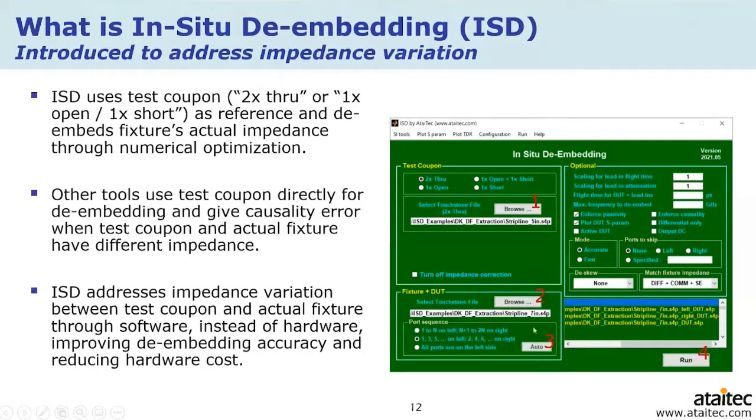It's going to give you a summary of the port connection and frequency number, etc., and then it's going to set the port sequence automatically. If it appears something different from what you thought it should be, then you can go back and check your data or reorder your port sequence, etc. And then step 4, you just click Run, and it creates the de-embedding files by default from the left side and also from the right side, and then the DUT file by itself.